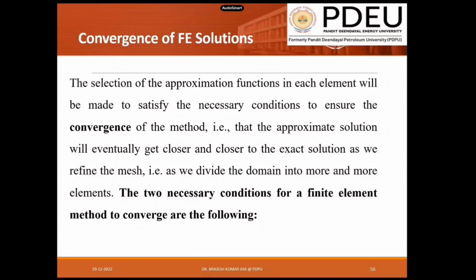Okay, so in the last few minutes, I will talk about the convergence of the method. So approximation of the element is very well defined according to the finite element method, but the thing is your solution should converge. The convergence of the solution is very important so that it will match the exact solution or be close to the exact solution. So mesh refinement can be done. One way is mesh refinement. Some necessary conditions for the FEM method to converge are as follows.